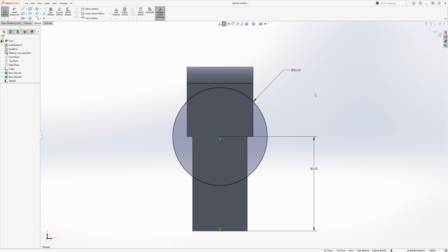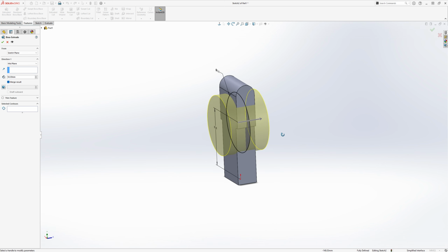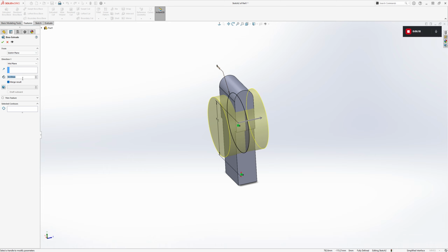Because we're making an extrusion inside of an extrusion, we need to make the cuts after all the extrusions are finished. So from here we would say feature extrude, and this circle will be extruded by 55 by the midplane. Select OK.